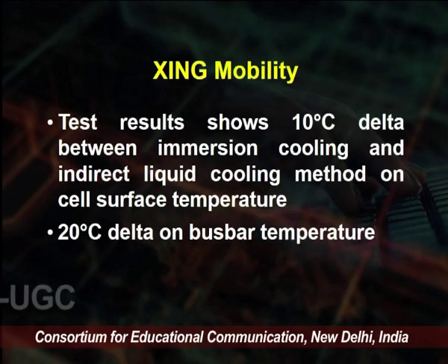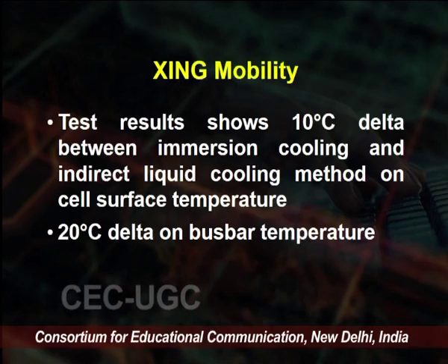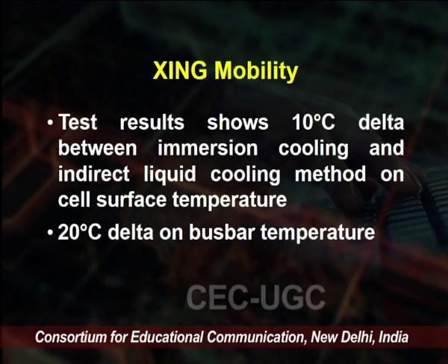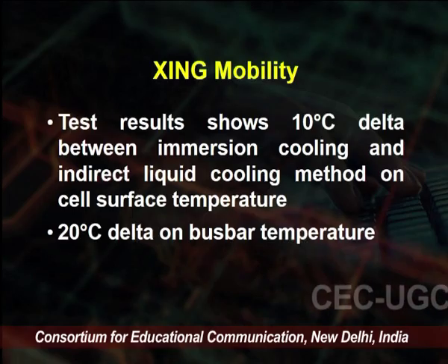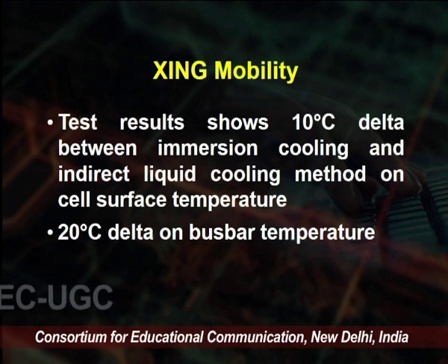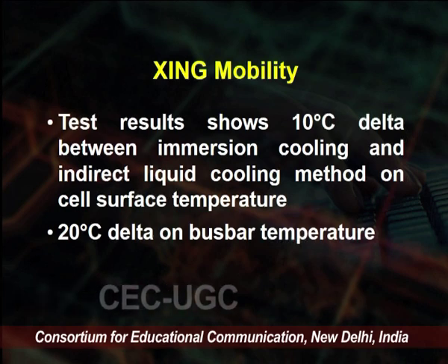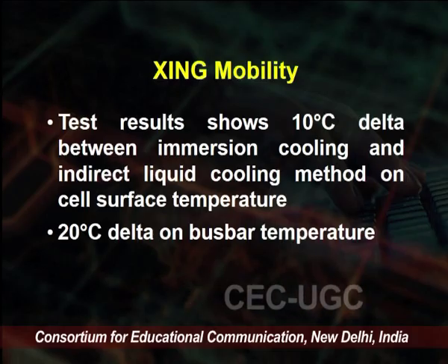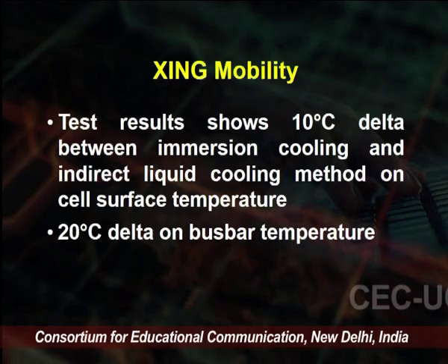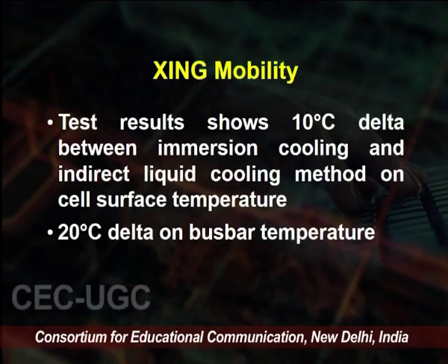Now another dielectric coolant is used in Zinc Mobility. Test results show a 10 degree centigrade delta between the immersion oil and indirect liquid cooling methods for the cell surface temperature, and a 10 to 20 degree delta on the bus bar temperature.